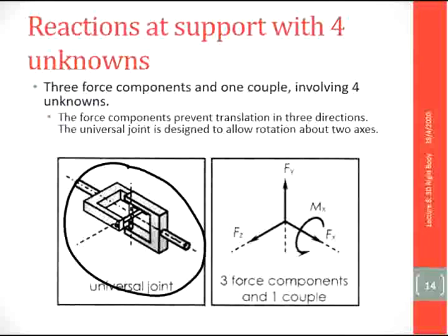Can this structure move toward the x direction? It cannot move, so there is a reaction ax here. It also cannot move up in the y direction, so it has a reaction ay, and it also cannot move along the z axis, so we have a reaction az.